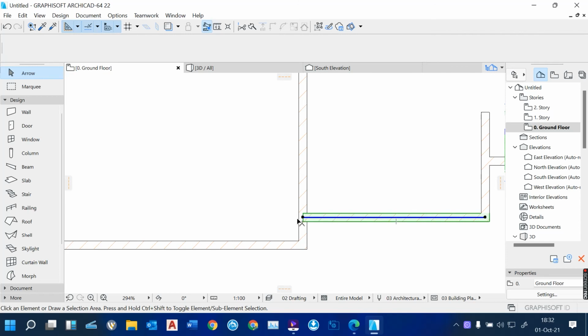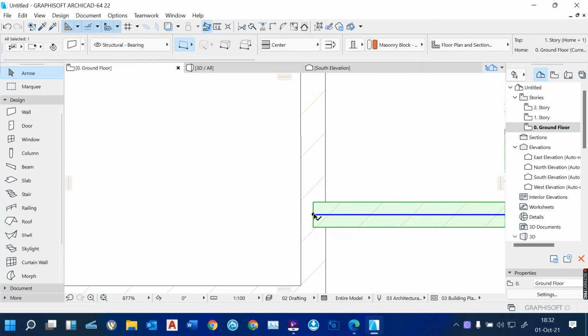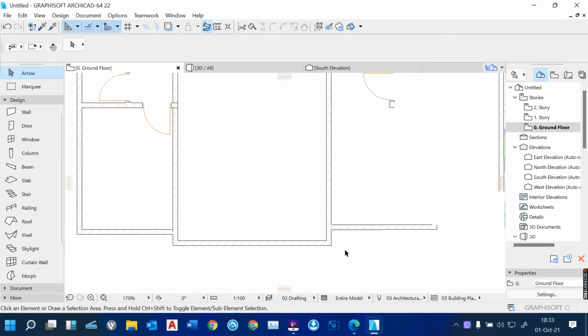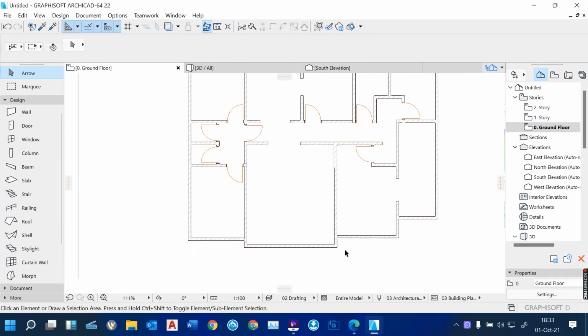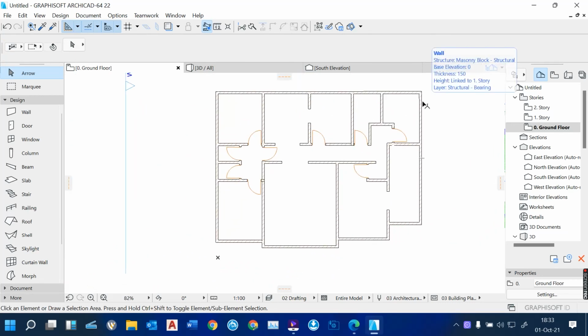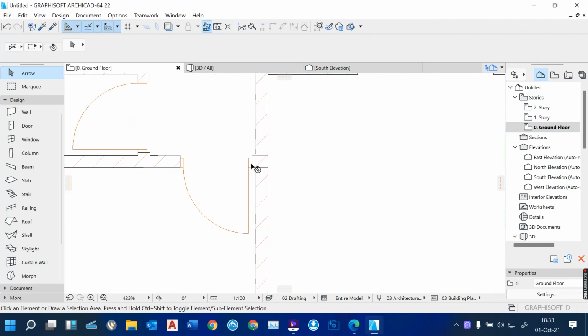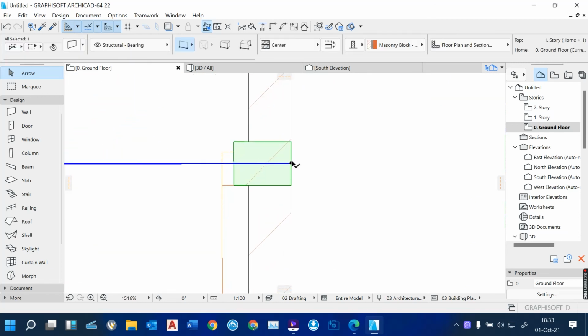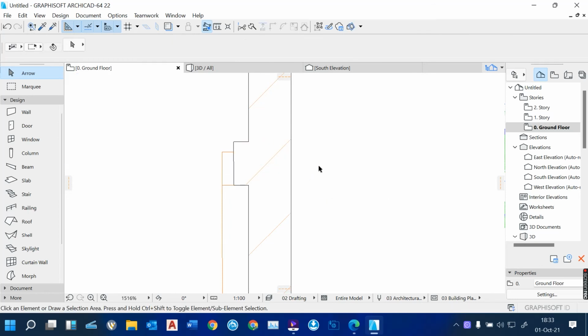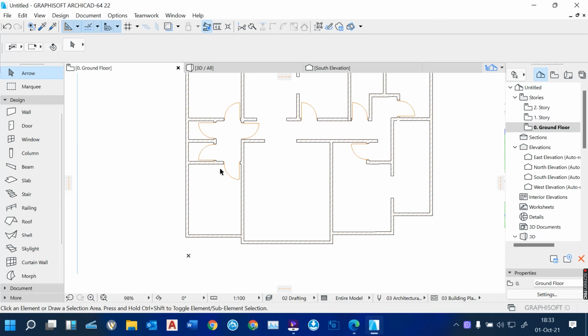This is the plan that we are going to use to design a simple project in Archicad. So having done all the doors and openings, walls and trimming of doors, trimming of walls, this one you can just stretch a little bit when you click on the node so that it connects with the other one. Yes. So we placed our doors.